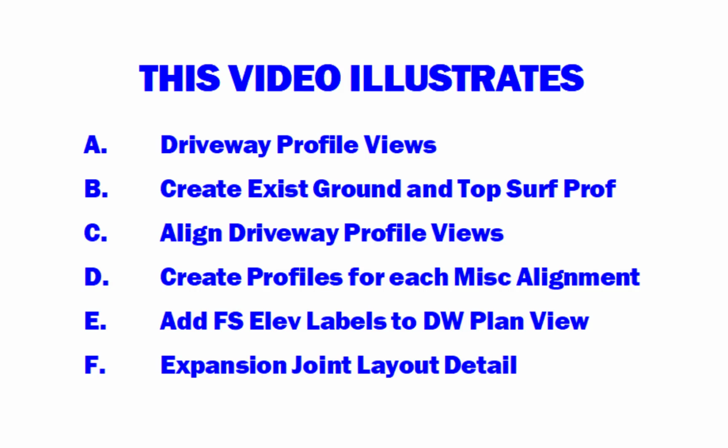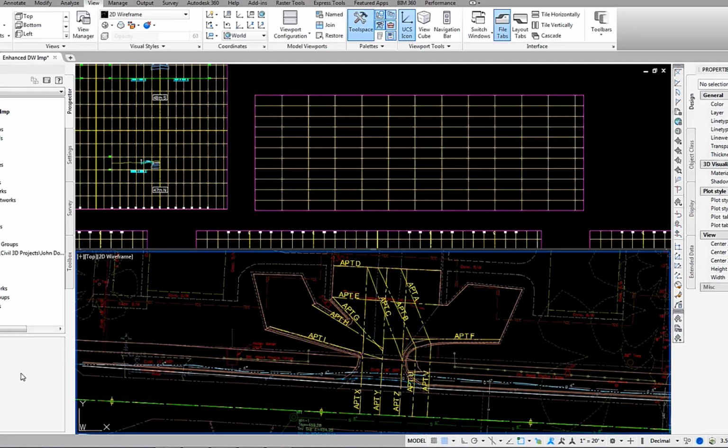F. Expansion joint layout detail. Enhanced driveway profile views are created separately for each alignment and are placed on the profile grid sheet in groups with vertical stacks of profiles. A group contains the alignments that are somewhat parallel with each other. A vertical stack contains the profiles for that group. Profile views line up vertically along 10+00.